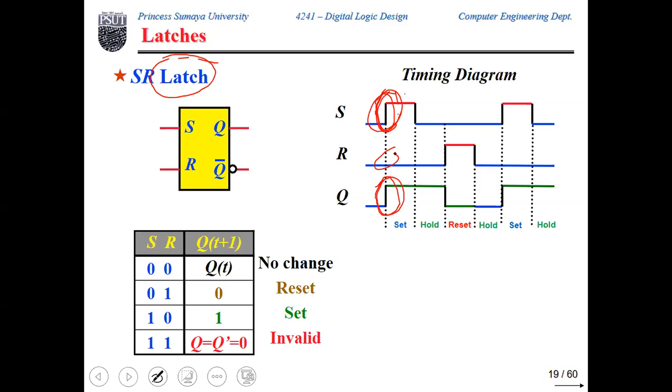So this is what makes the difference between latches, clocked latches, and flip-flops: when the stored value is affected by the external inputs. In latches, this happens immediately. Theoretically, as soon as the input changes, the stored value can be affected by the change.